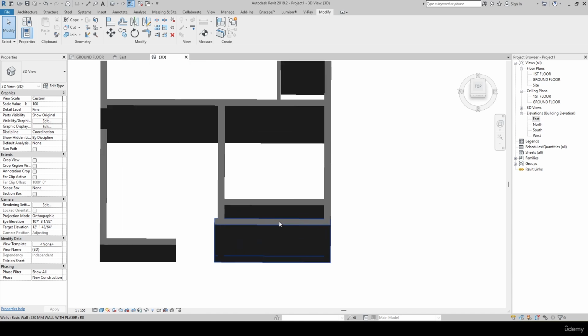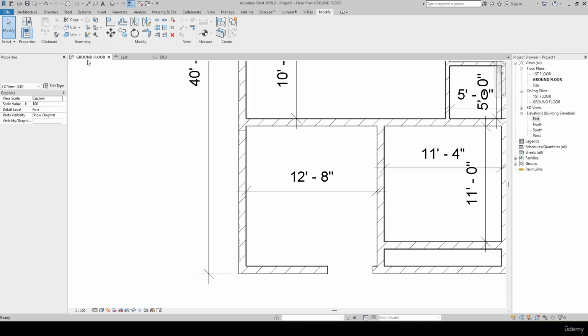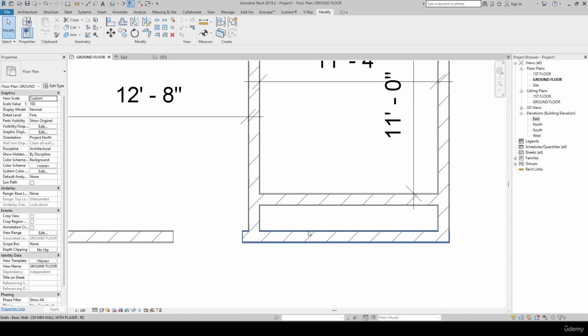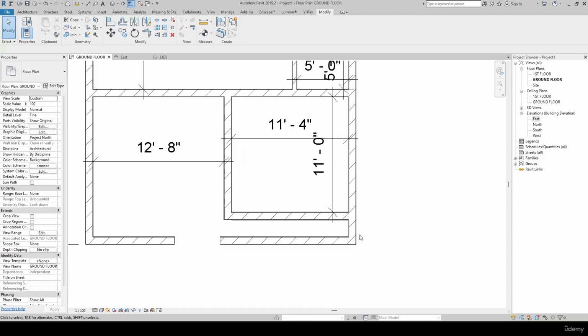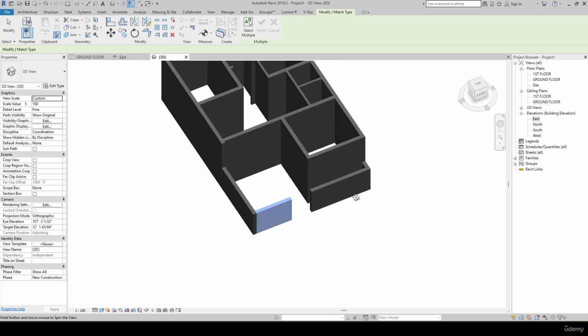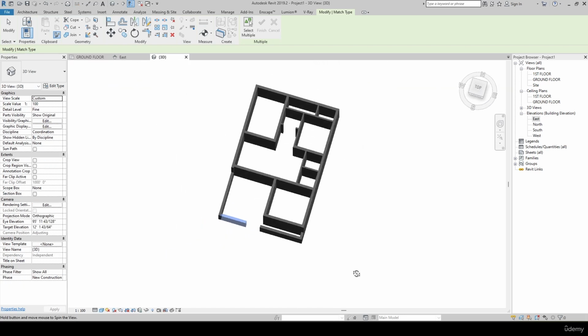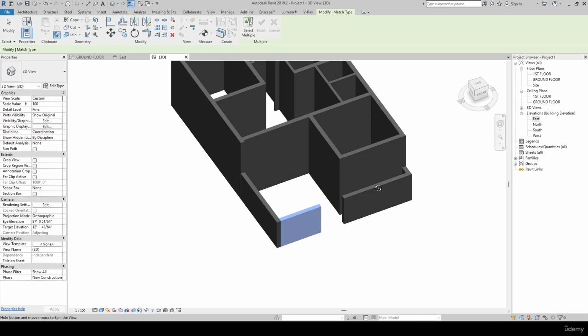So basically in the front, this also I need to reduce. Okay, then again I'll add the split element. I'll cut somewhere exactly here and here as well. I delete this wall and again I split, SL. I split somewhere here. I use the MA command to match, then I match this and again match this. I'll go to the 3D. You will have this kind of view. Okay, this is a raw drawing which I'm making for you just to understand the command usage.